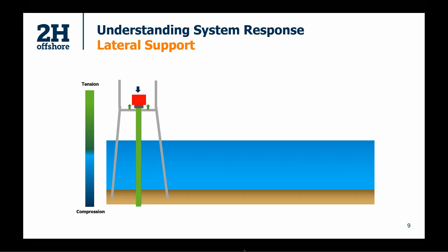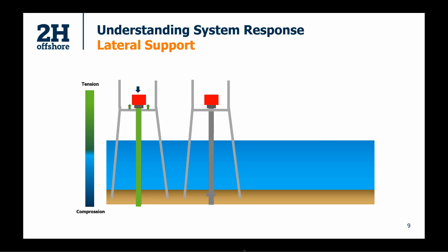But what you often find is that it's not possible to simply apply tension. It could simply be that you don't have enough deck space to get the tension system in there, and therefore you're not going to be applying tension. So we need to look at what we can do to limit the susceptibility to buckling.